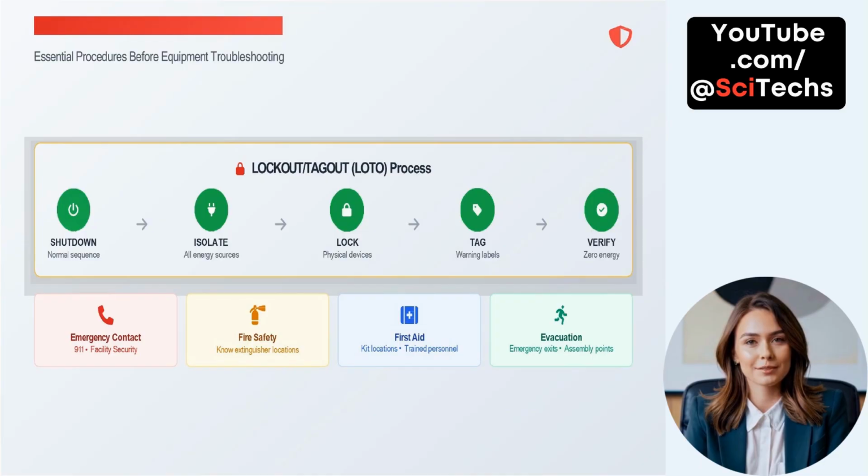Essential procedures before equipment troubleshooting. Before troubleshooting any equipment, it's critical to follow the lockout, tagout, or LOTO process to ensure personal safety and equipment integrity. Begin with shutdown. Turn off the equipment following its standard shutdown sequence.